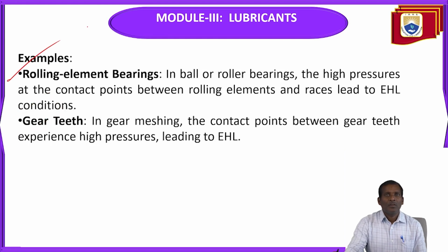Examples: rolling element bearings. In ball or roller bearings, the high pressures at the contact points between rolling elements and races lead to elasto-hydrodynamic lubrication conditions.